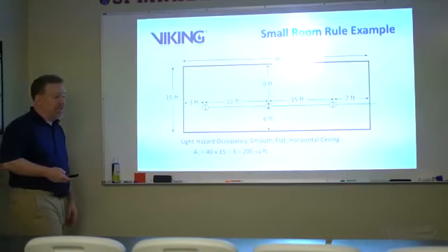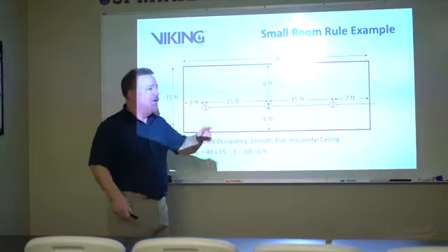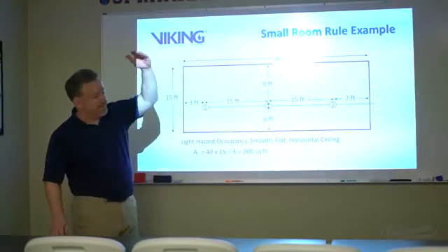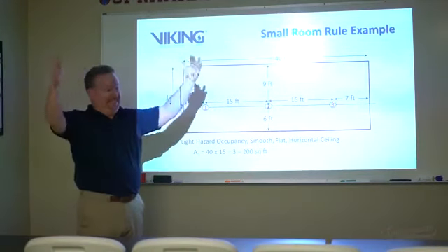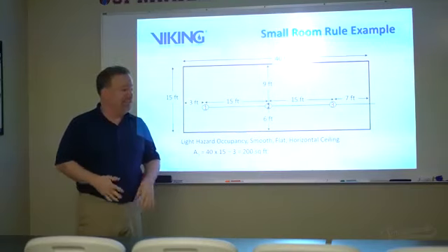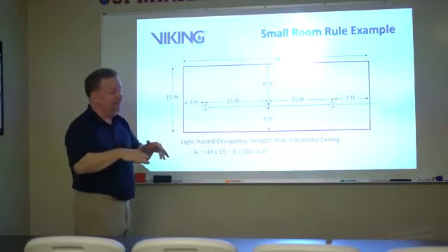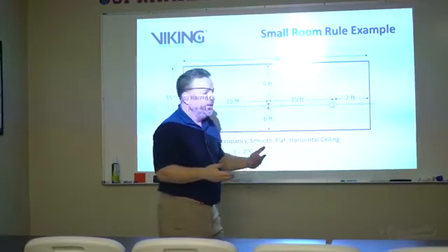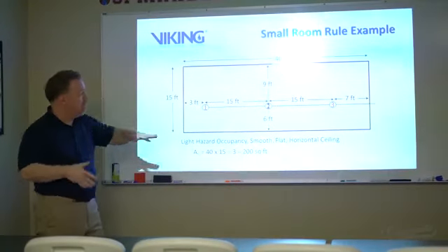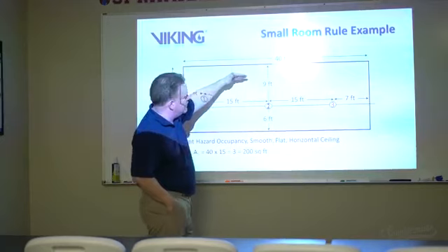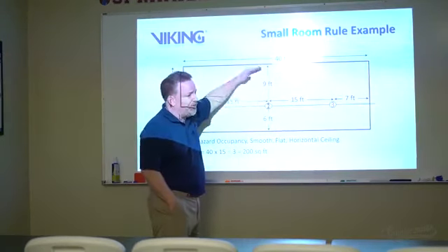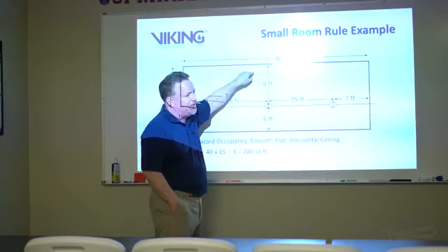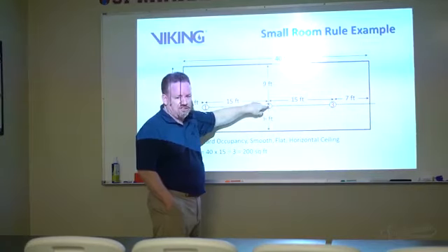The lintel depth is important because what does a lintel do at the ceiling line? Traps the heat. Collects the heat. So what we don't want is a whole lot of this heat escaping the room where it's not being collected. Okay? So remember, by virtue of the fact that we've got a sprinkler that's 1.5 feet further away from the wall, if we get a fire starting over here, what's that going to do to the operation time?